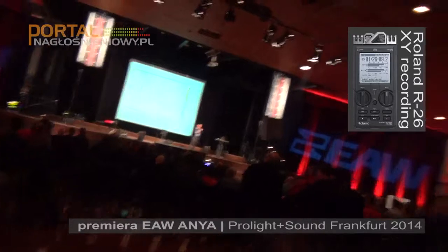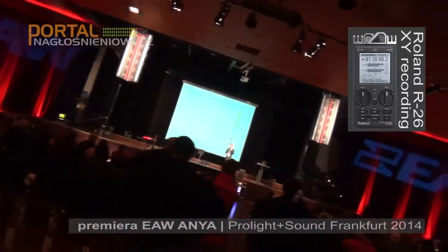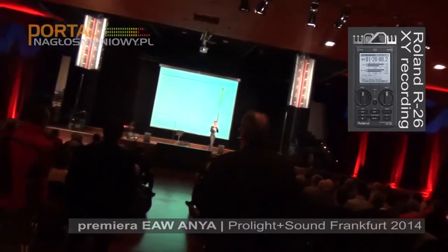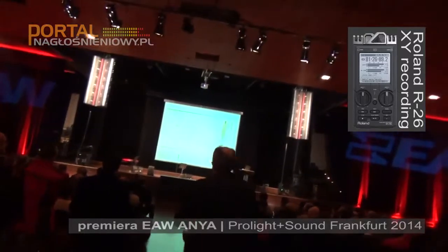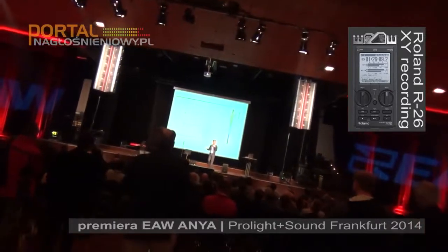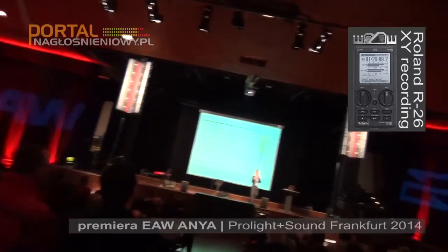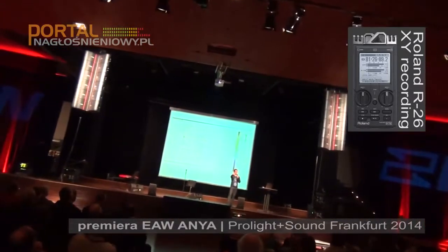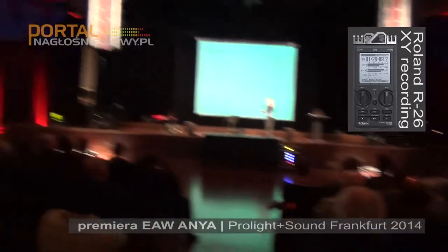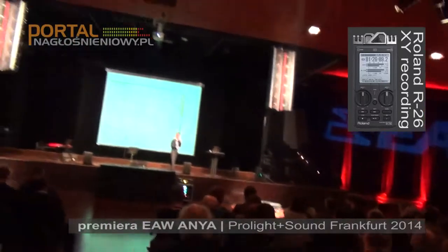One of the things that we all know is that the throw differential from near to far, front to back, is much greater than what we have left to right. This is one of the reasons for the predominance of line arrays in our industry today. A line array system does a very good job at tailoring the sound to be fairly even from the front of the venue to the rear, but it really does nothing in the horizontal plane. And in fact, we've given up something that we used to all have with the horizontal arrays of years ago.